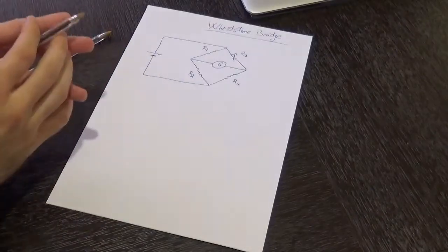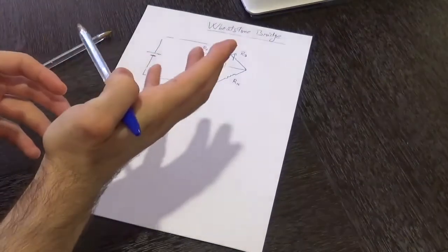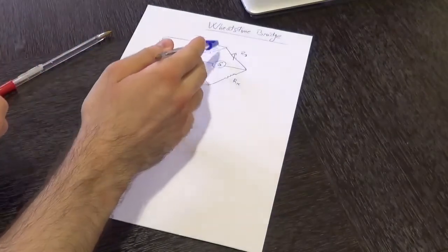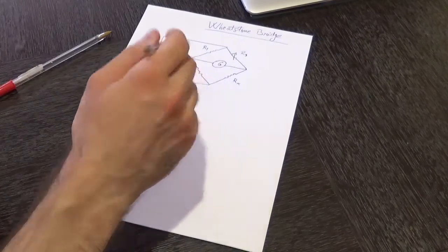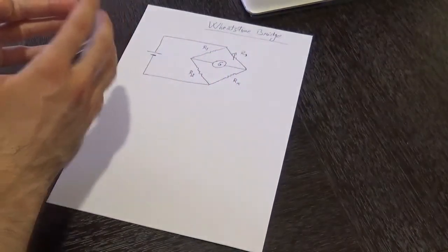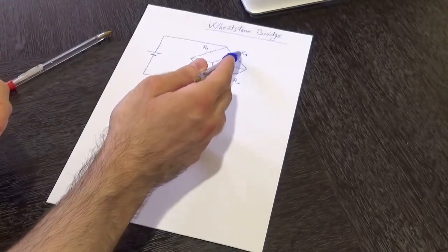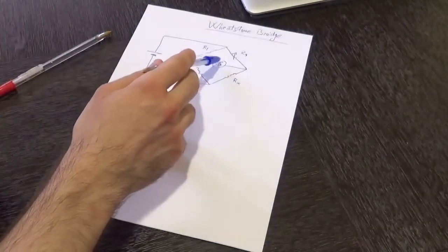Now let's move on to the Wheatstone Bridge. That circuit over here, which consists of 4 different resistors, is the Wheatstone Bridge. So we have resistor R1, another resistor R2, a third resistor Rx, which is an unknown resistor, meaning a resistor that we don't know its value and we need to determine its value of resistance. And then we have a variable resistor R3, which is basically a potentiometer. And then in the middle over here we have a galvanometer.